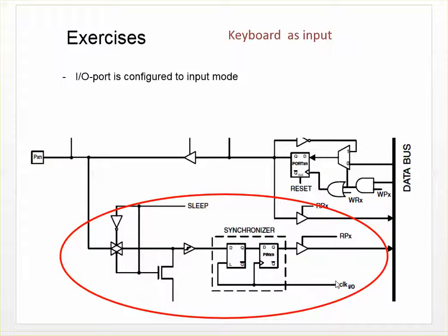And here are these clock signals. These are used to synchronize these latches. This has minimal functionality for the basic idea; it is only to synchronize the input signals to the same time base. And this sleep circuit is used to put the processor in sleep mode so that it doesn't drain any current from the batteries.